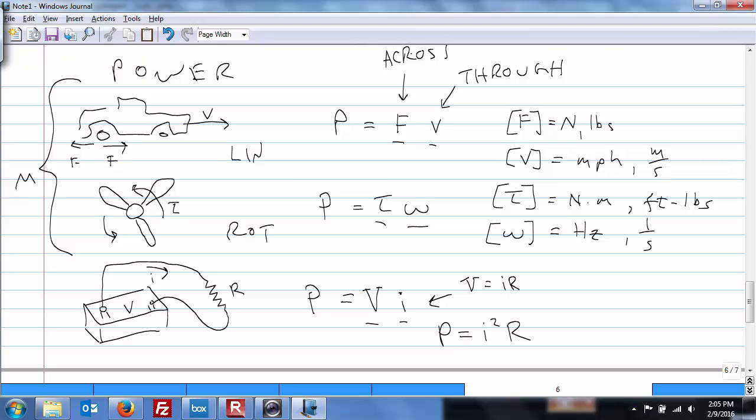You hear a lot of times, like, Montana's got this problem because it's so big, Colstrip's way over there, electrons have to flow all the way through these. It's just turning into heat. That's the loss. If there were no resistance, if you had superconductors, some metal that was better than copper, R would be 0, and there would be no power loss. That I squared R is just called Joule heating.